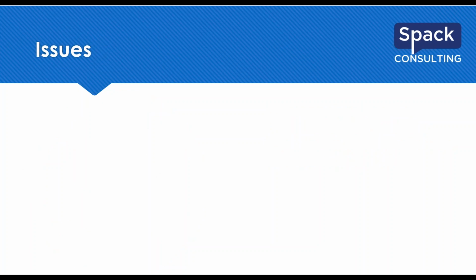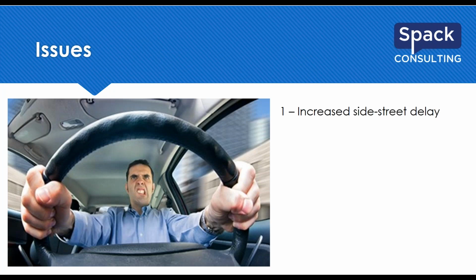All right, so on the flip side then, what do you need to be concerned about as you're looking at signals and removing them? Yeah, kind of the opposite of the first one of the benefits is, we have a photo of Bryant behind the wheel here, is... Not quite me, but if I've been there. If you remove a signal, it will increase side street delay because you're all of a sudden at a stop sign, so you've got to wait for the main line to get through. It may increase side street delay.